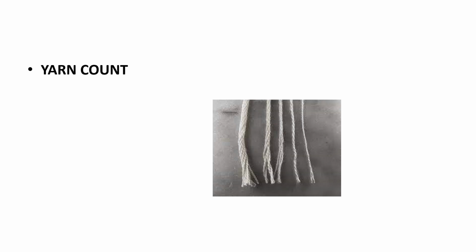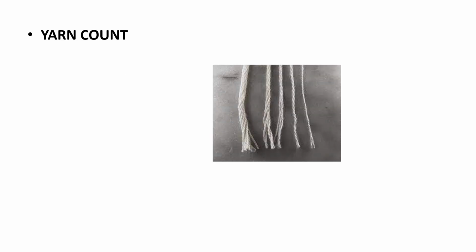It is very important because when you are stitching different assemblies or panels in the sewing machine, the quality of the yarn plays an important role, and the sewing thread is really responsible for it, depending upon the yarn count. Different yarn counts, fineness and thicknesses are there in this industry, and we have to use them accordingly.